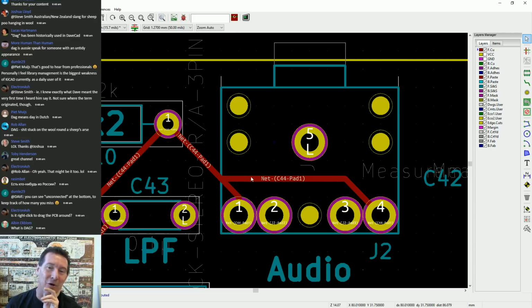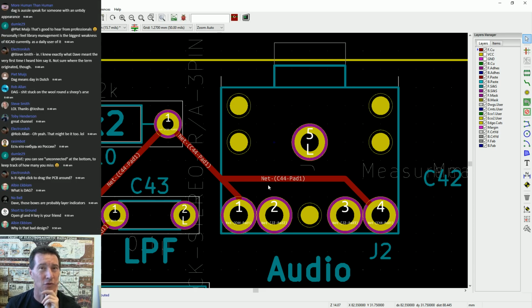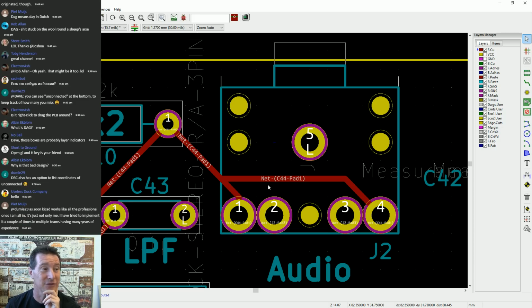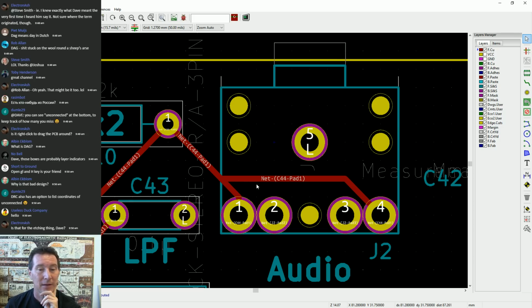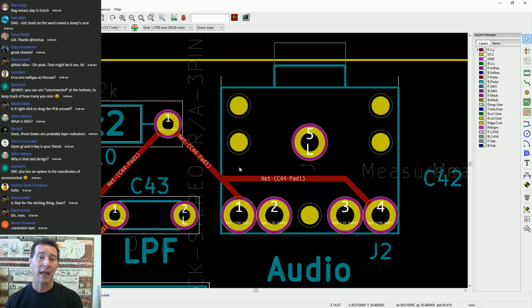It just goes back to the reason that you don't have sharp angles like that. It's not so much an issue these days because the process controls on manufacturing boards are stunningly good. But back in the old days, and it's still the case, when the board's in the etch bath getting etched, they use a bubble etch, so it's all bubbling and swooshing around in there.